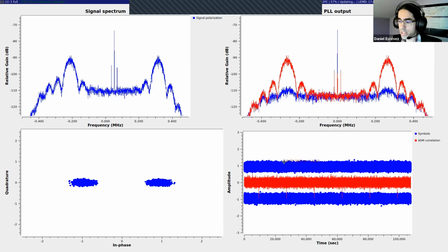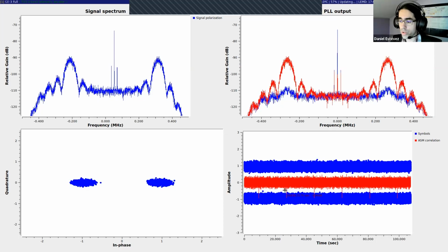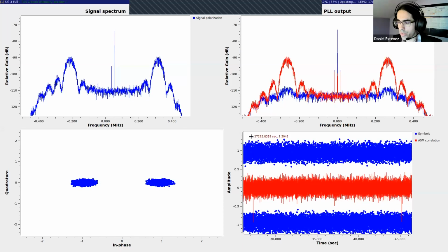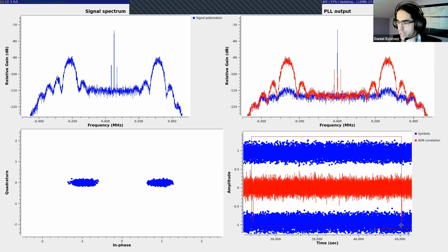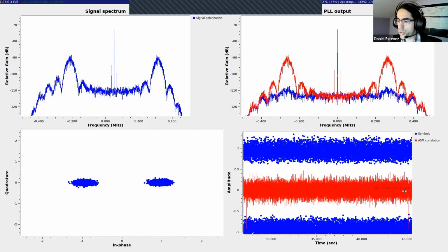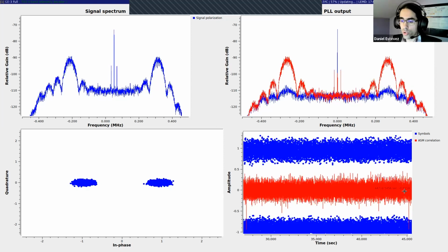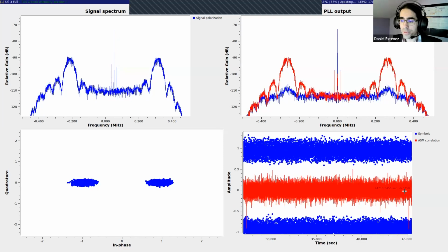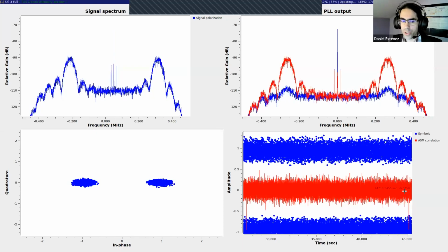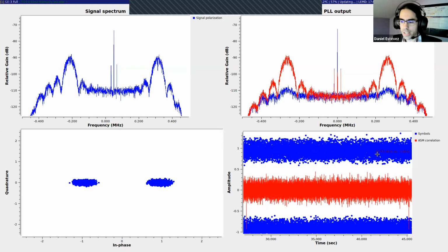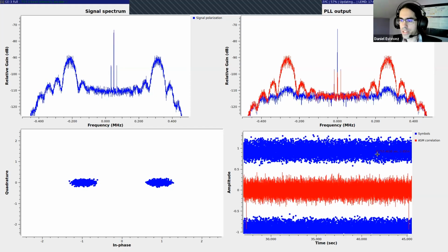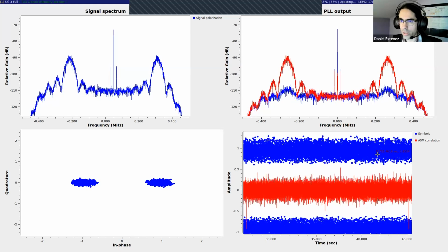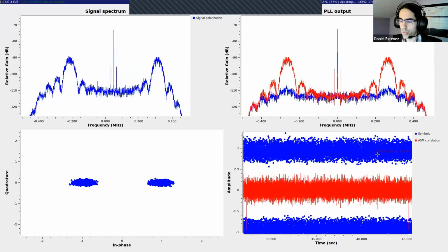So what is happening at this stage is that the receiver is finding these attached synchronization markers, is selecting the bits between them, as if I were to do some kind of selection like this, and it's sending those bits to the turbo decoder, which is then doing some clever statistical analysis to try to figure out, given what we have observed in the signal, what would be the most likely message that has been transmitted, even if there are some errors in what we observed. So that's how error correction works.